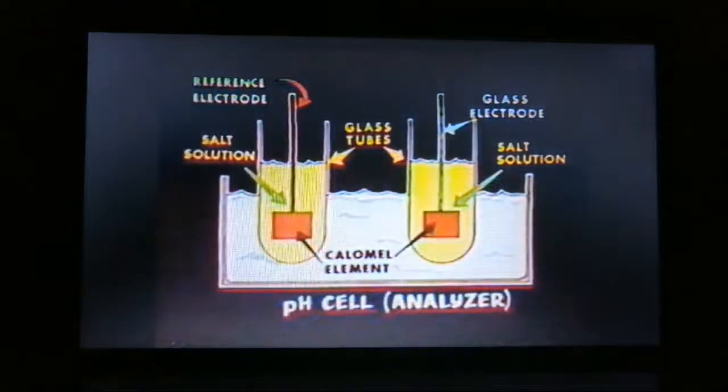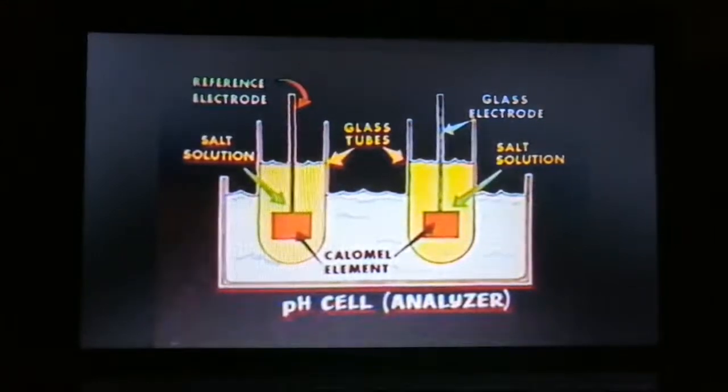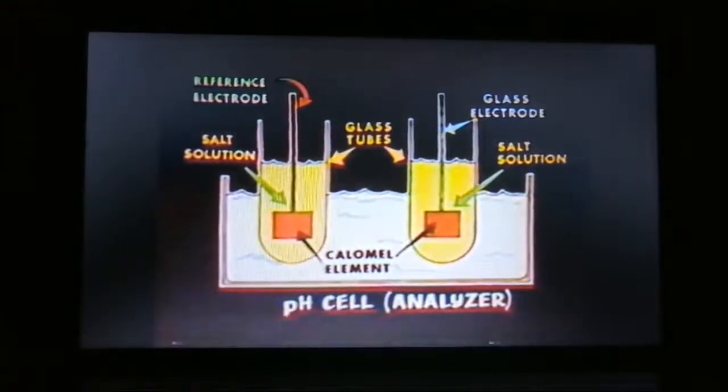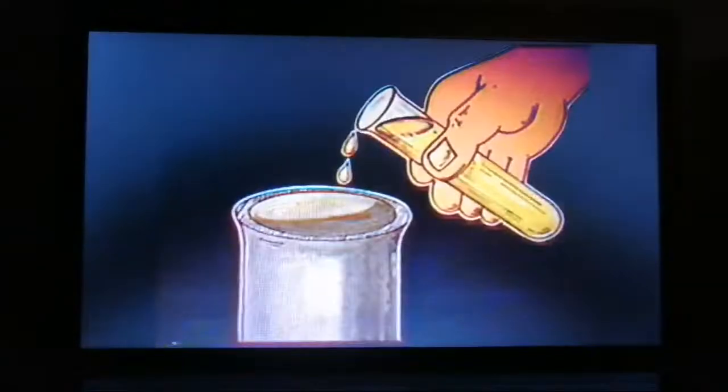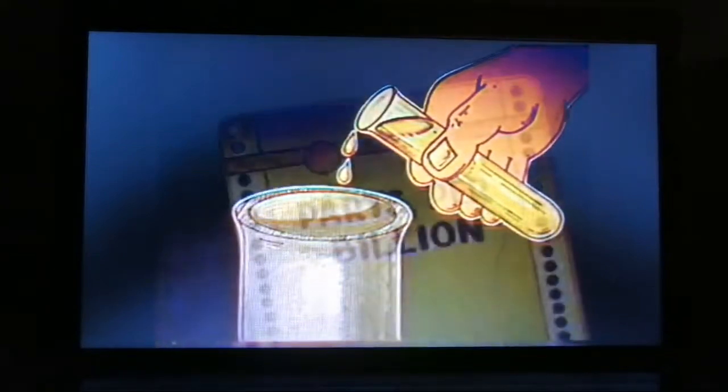It is also important to measure the pH of the condensate. pH metering devices measure the amount of acidity, or its opposite, alkalinity, of a solution by means of probes or electrodes. The pH meter reads degree of acidity or alkalinity on a scale where a reading of 7 is neutral. to keep the water and steam from changing pH rapidly, and to slow down the action of water in trying to dissolve copper and iron from the pipes.